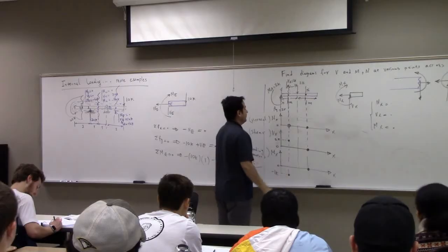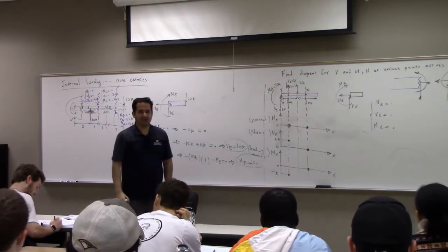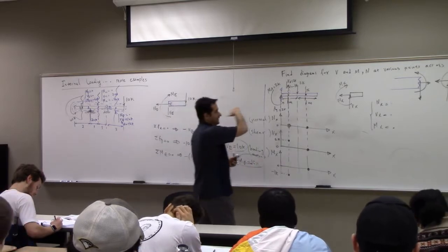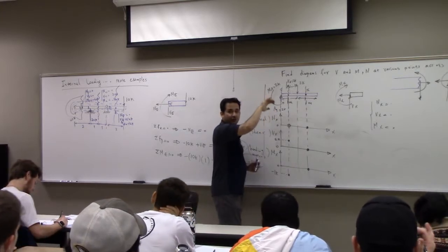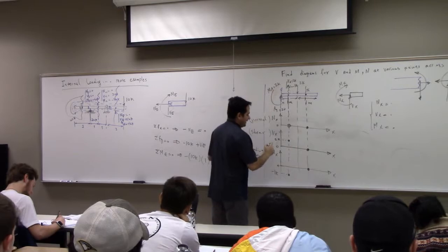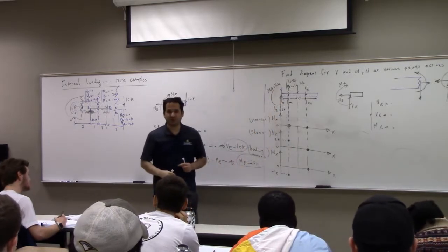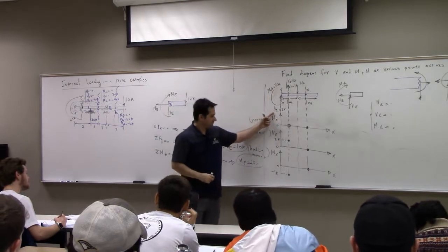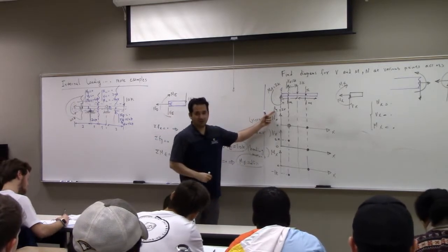If you do point A, what is your bending moment? 2K is the one that the external surrounding is applying to the structure. The internal load is going to be negative 2K. What about the normal force? 0. What about the shear load? The shear load is going to be 2K, right?